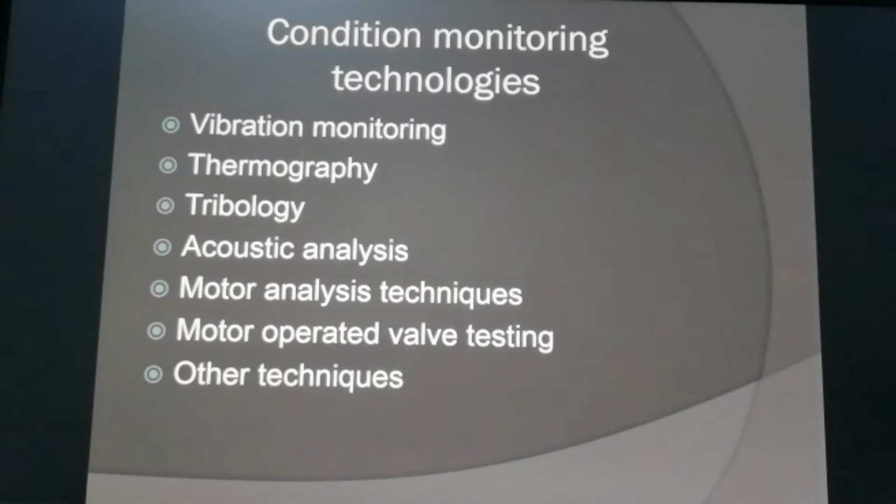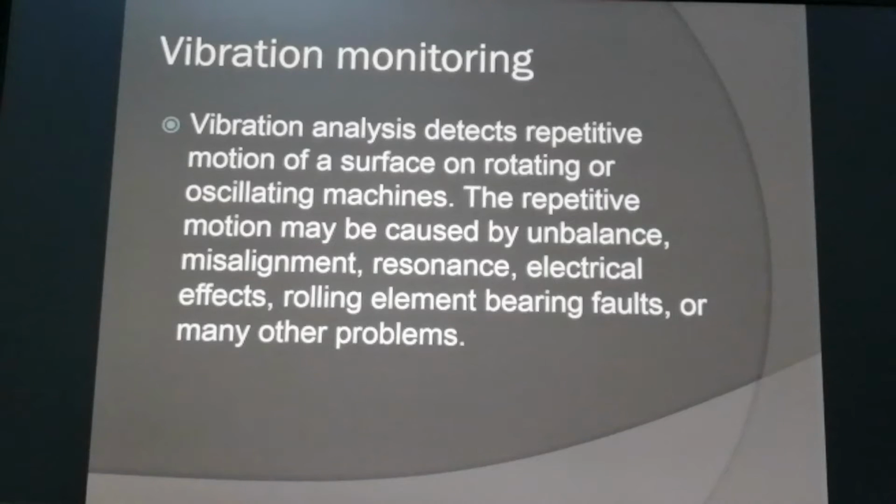Condition monitoring technologies: vibration monitoring, thermography, tribology, acoustic analysis, motor analysis technique, motor-operated valve testing, and other techniques. Vibration monitoring. Vibration analysis detects repetitive motion of surfaces on rotating or oscillating machines. The repetitive motion may be caused by unbalance, misalignment, resonance, electrical effects, rolling elements, bearing faults, or many other problems.